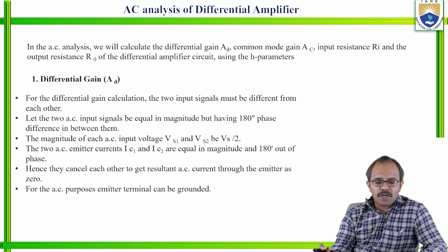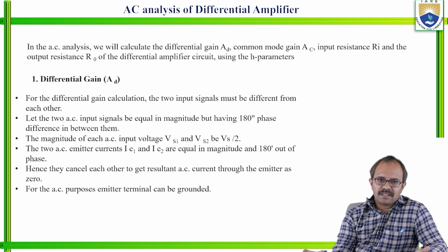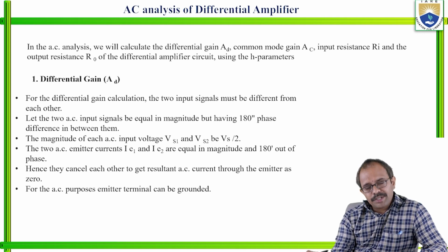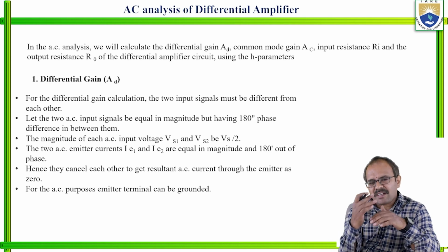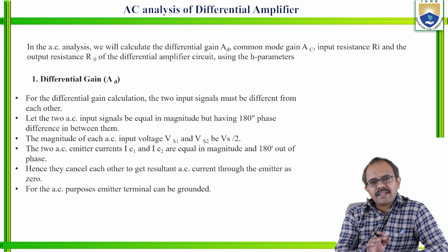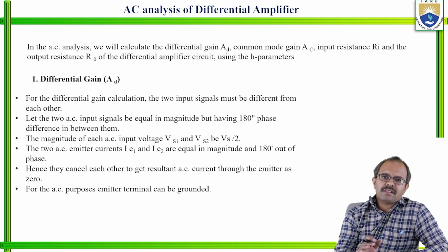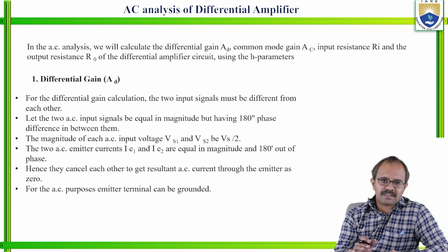Before concluding this session, I will brief the AC analysis. What we are going to do, how we are going to perform the AC analysis. It is just a reverse operation, I can say. In the DC analysis, all the AC components were suppressed, and in the case of AC analysis, all the DC components will be suppressed, right? So that is the first step here.